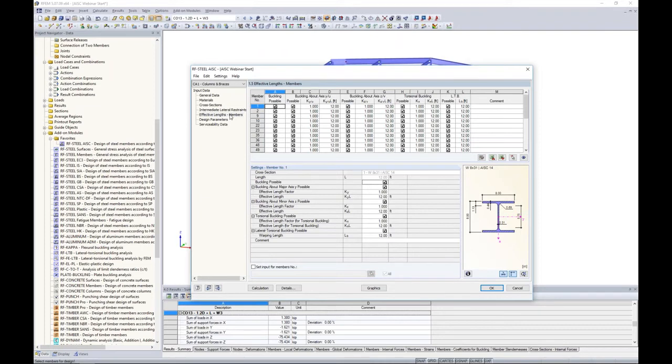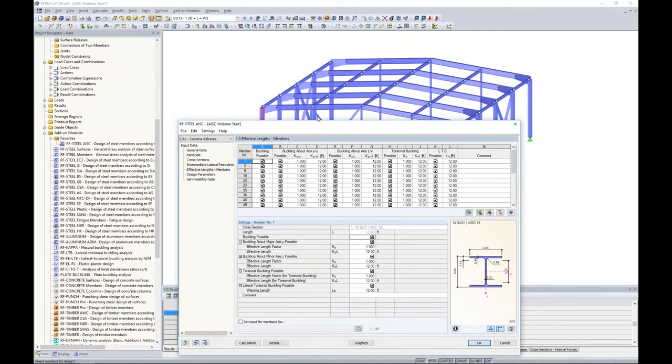And I can't stress enough how important unbraced lengths are. As a software program, the program is only smart enough to know the unbraced lengths as you've entered them into the program. Meaning you can see right now that our unbraced lengths, which would be this column, we have a few columns here, buckling about the strong axis, buckling about our weak axis, torsional buckling, and lateral torsional buckling. We have the column here for our K values and our K times our L. Now this is our unbraced length times our K values.